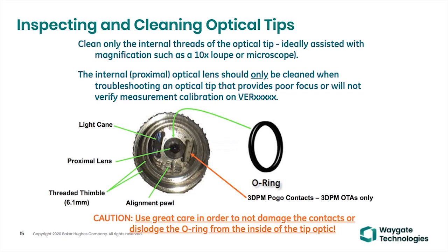It's best if you use distilled or some kind of filtered water, not standard tap faucet water, because you'll get the alkaline and hard water buildup over time. Clean it with clean water, preferably distilled water, a couple of drops of dish soap, rinse it out, and then air dry it. So it's those pins that you want to stay away from. You don't want to wipe them down with any mechanical instrument. Just rinse them off if needed in the way I just described.